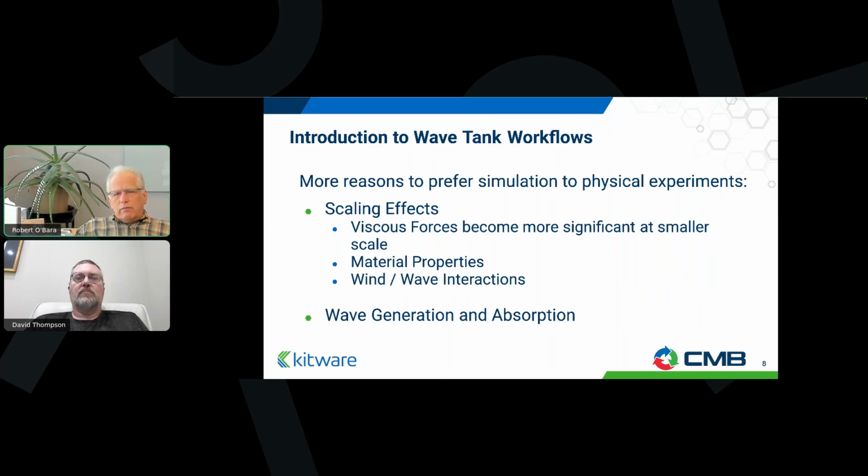They can become much more significant at smaller scale. So if I reduce the problem, I'm going to introduce some inaccuracies inside of my simulation, as well as with things like material properties. They may not scale properly if I'm going to 1/100th or 50th scale, as well as monitoring things like wind-wave interactions.